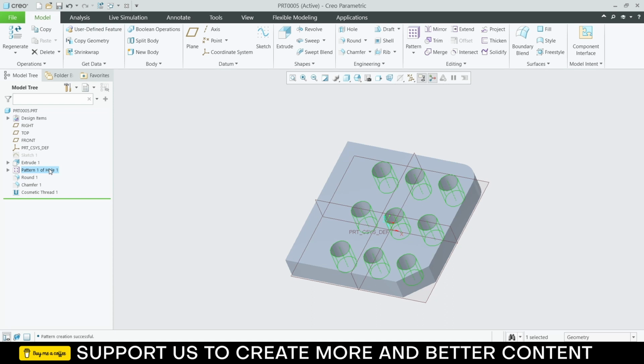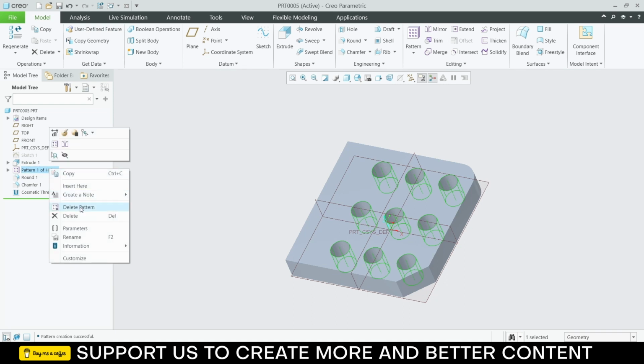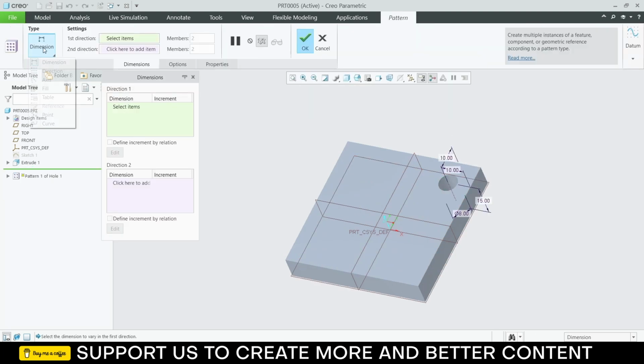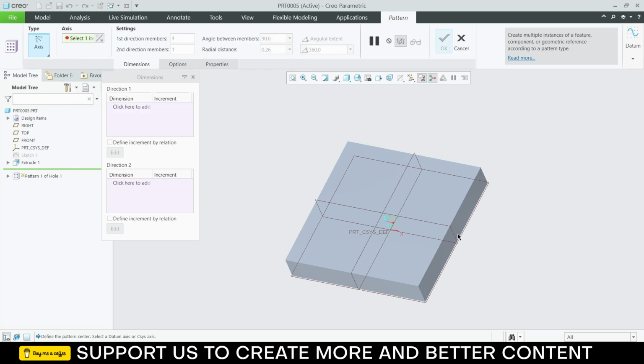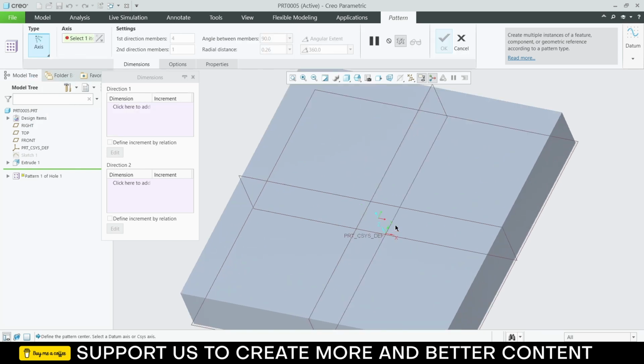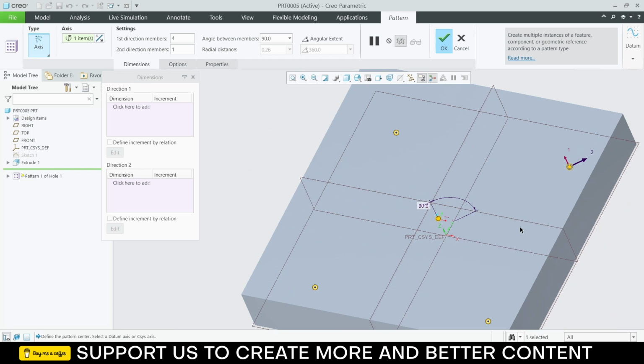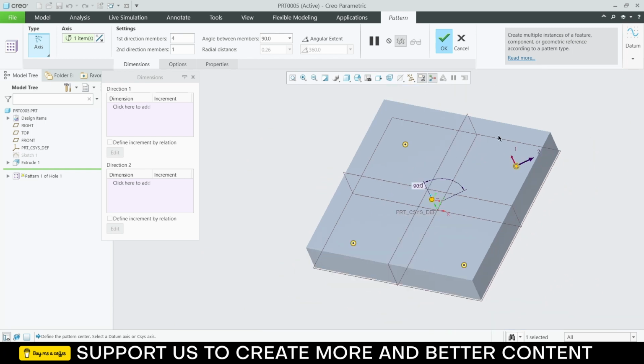So right click and click on delete pattern. Select this feature, click on pattern, and now I will choose axis. Axis basically means circular. If I zoom in, notice this gizmo. This is the center of origin. If I select the Z axis, it knows that it has to rotate about this.